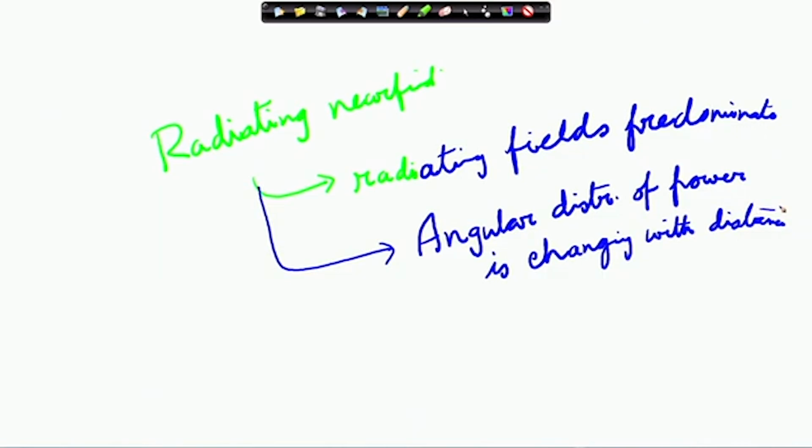That means the radiation beam has not been formed yet, it is still forming. That is why if you measure the power pattern there, and then measure in that zone at another distance, you will see a different pattern. So, there is no standard pattern in that place. That is called the Fresnel zone, and that is why it is important. If you want to put your antennas in the Fresnel zone, you need to be very careful about the distance from the antenna.